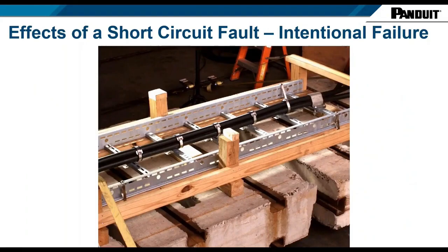You can see here we've got 3 single phase cables laid in trefoil. This is a standard IEC testing rig. You can see the 5 cleats in the center of the picture there are our tested cleats. We need at least 5 to comply to the standard.